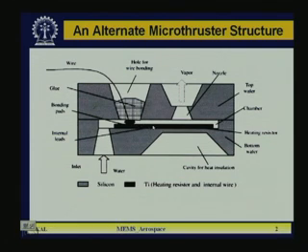Obviously you cannot see the total meander line, only some black patch you can see, and they have two leads. In the top wafer, other than the nozzle, they have etched another hole, and through that hole they made the wire bonding. And after making the wire bonding, taking wires outside from the titanium heater, they fill the hole at the end using some glue, so that it is completely covered. So in that case, you can directly heat the element.